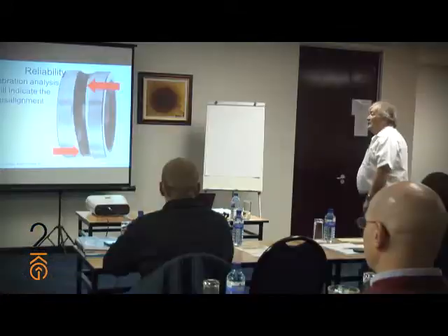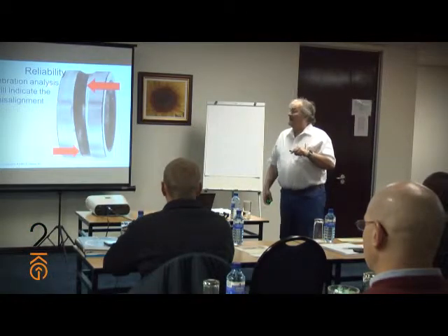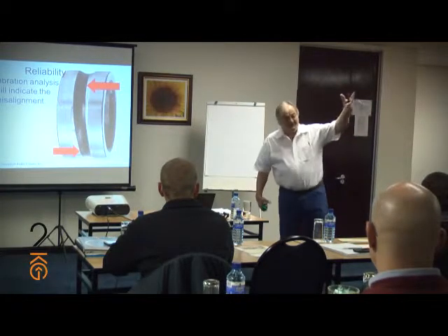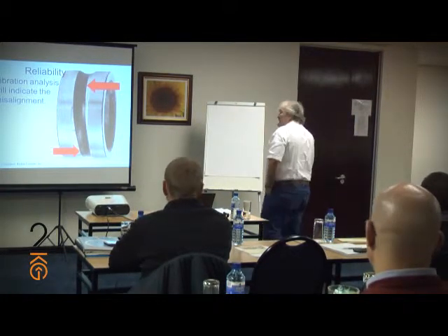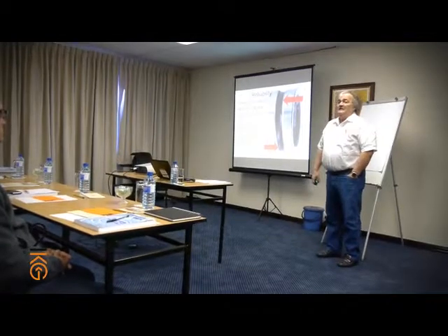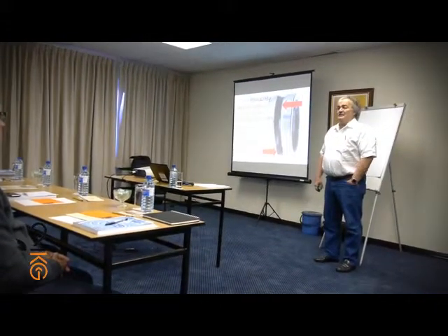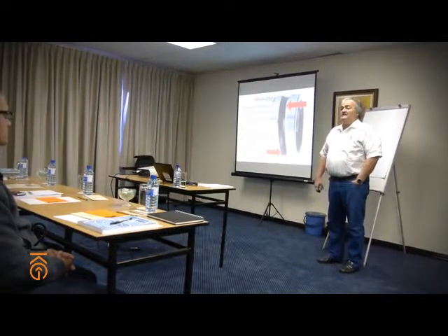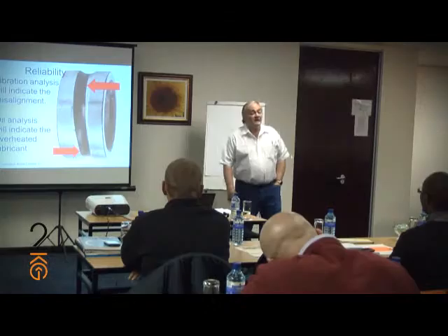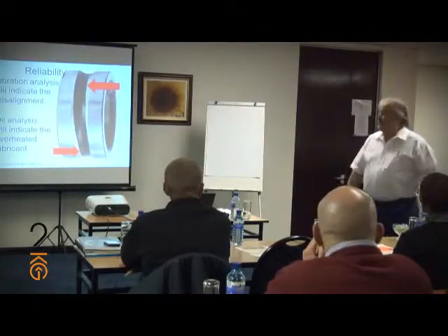Now, many plants have vibration analysis. Raise your hand if you do vibration analysis where you work. Most places do these days. So vibration analysis will indicate the misalignment. Many places do oil analysis these days. They will send samples of the oil to the laboratory, and they will say there's copper or iron or stainless steel shards, microscopic shards in the oil. So this is why we do oil analysis, all in an effort to determine what's going wrong with the equipment.